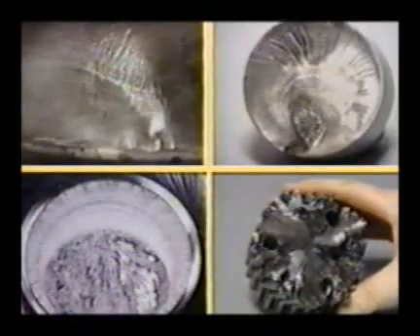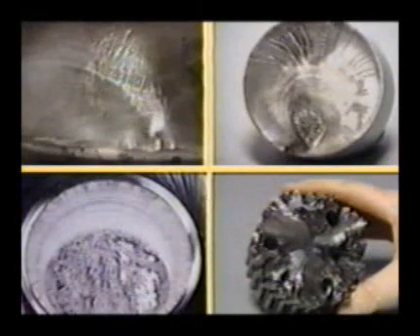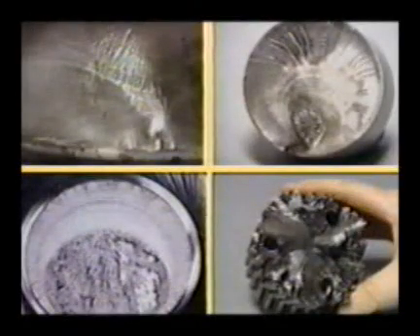Occasionally, a fatigue crack will break up into several smaller cracks in the middle of the fracture due to changes in part geometry or increased stress. If these cracks recombine into a single crack, a series of ratchet marks may be formed. It is not critical that you remember all the different beach mark patterns and the loads that cause them. The purpose of these examples is to help you recognize the characteristics of high-cycle fatigue fractures.